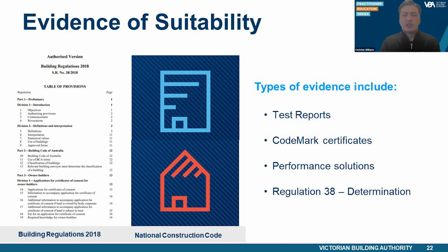Under the National Construction Code from the 1st of July 2021, compliance with clause A2.24 is required, meaning all performance solutions must follow the process of preparing a performance-based design brief and a final report. The relevant building surveyor should not be involved in the performance-based design brief, as they must have no involvement in the design of the building.